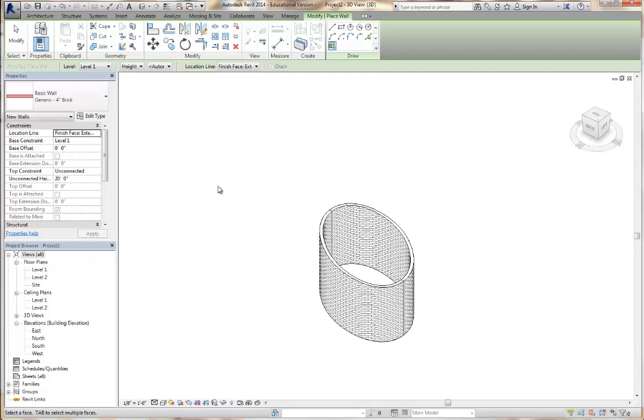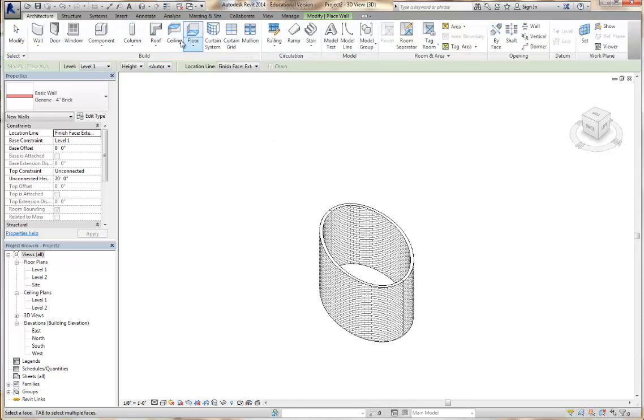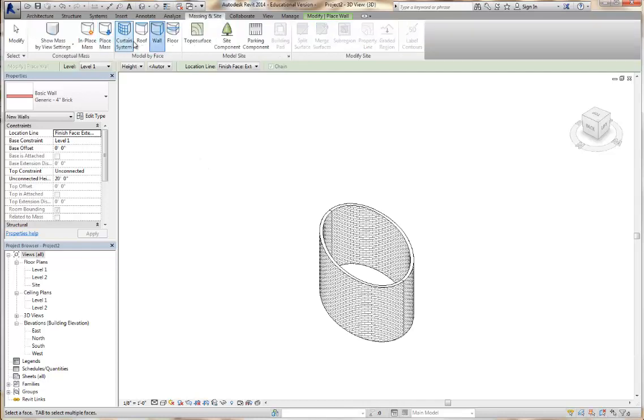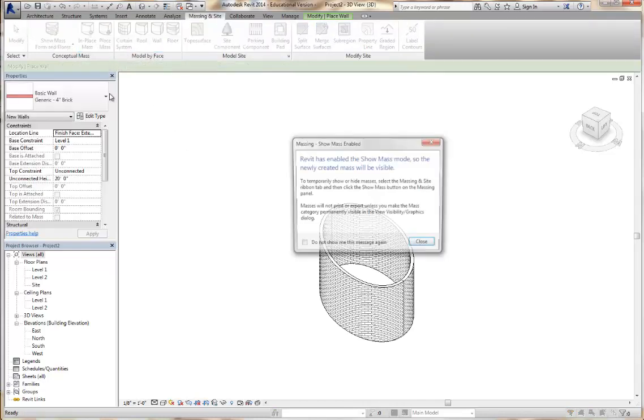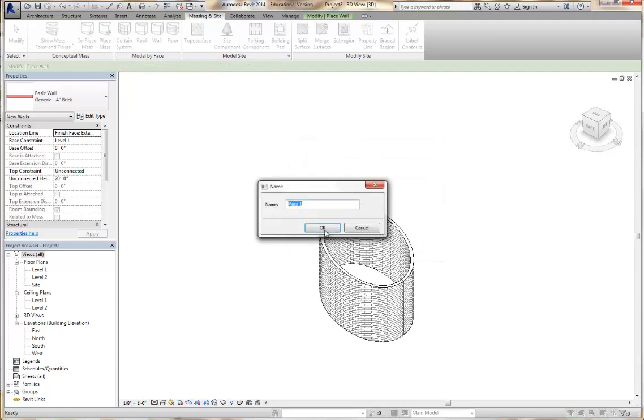You used to be able to do this in the exact same way in Revit by basically developing a SAT file and dumping that in. For whatever reason I was trying that out and I couldn't get the roof by face to actually work and generate the roof. It tried to attach it as best it could, but it just didn't work. So we're just going to do it the longhand way, and what you're going to do with that is create an in-place mass. So we'll hit close, and we'll just call this the roof.